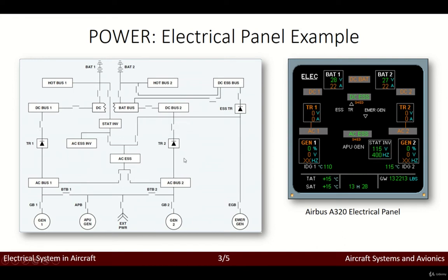So it basically means that depending on what fails, if there's some failure on the engine, for instance, if engine one doesn't work, then we have troubles regarding generator one, and troubles powering all the subsystems on this number 1 area. So we basically need generator number 2 to fulfill all the different subsystems, okay. And the way in which this is done changes from aircraft to aircraft, but basically you can see that there's always a strategy to make sure that all buses are covered, right?